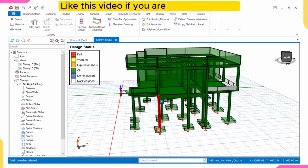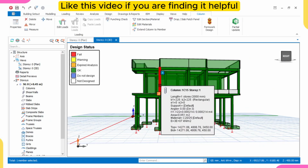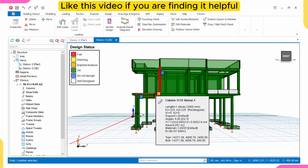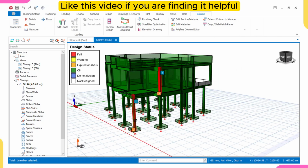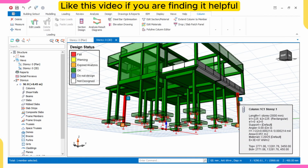Also, they are of the same height: this is 3 meters, this is 3 meters, this is also 3 meters, this is also 3 meters. If you check the reinforcement, they are of the same reinforcement. Everything about this column and this column is the same. So any column that starts from this base to here, all of them are column one because they are the same. Any column that just stops at the ground floor, which is this and this and this and this, is my column two.